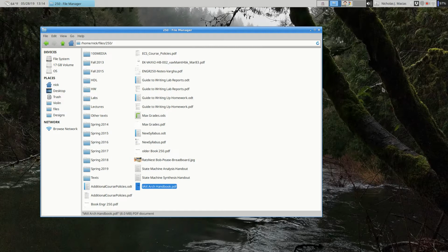And then you take that and you use a lens to reduce it optically, and you shrink it down to the size that you want. And you use that to hit photosensitive chemicals that will be changed by the presence or the absence of light. So now you shine light through this and you hit something that's been treated with these chemicals, and wherever there's a solid line drawn, it changes the material properties on that piece of the substrate so that it's resistant to a certain chemical. And where light goes through, you get pieces that are not resistant to that chemical.